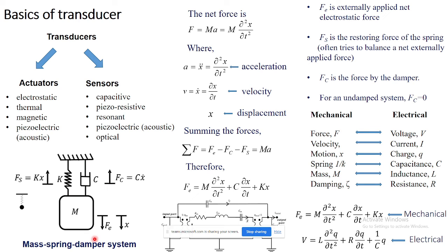When we have a graph, we should see a linear shift in the output with respect to the input. When we have a deviation from that, we calculate in percentage how much the non-linearity is. This is how I have characterized my devices. Yes, that's very close to what I was expecting. So when you design a new sensor, you define the amount of non-linearity it can have and still be a functional sensor.